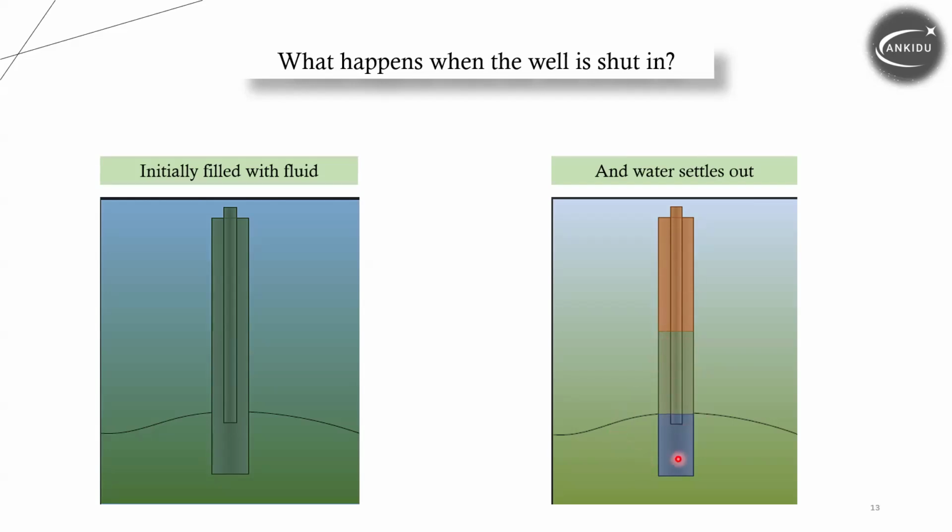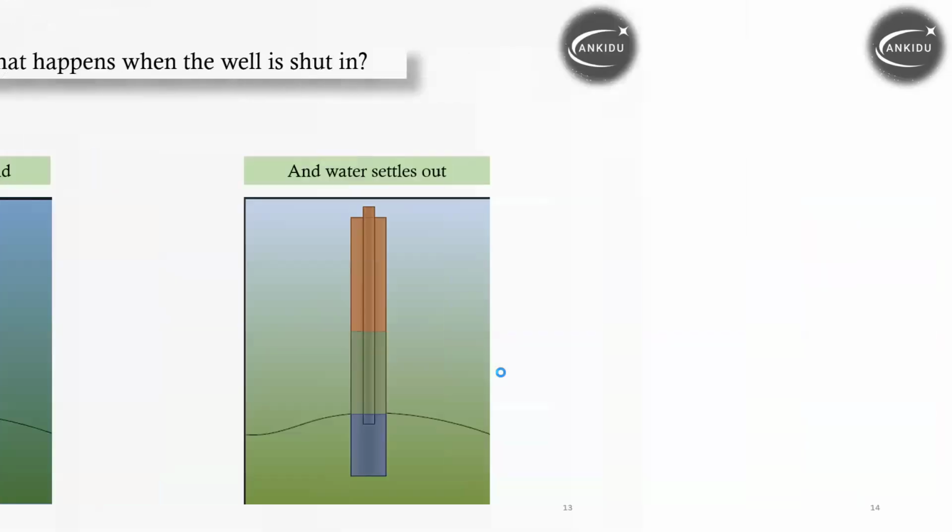So all these factors can play a crucial role in whether the well can be flowed again or not, because we know the hydrostatic head here is working against the flow. Is it low or high? So when we try to open the well to flowing, it creates a constraint for our well to be flowed again as natural flow.